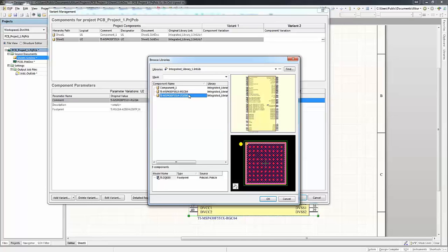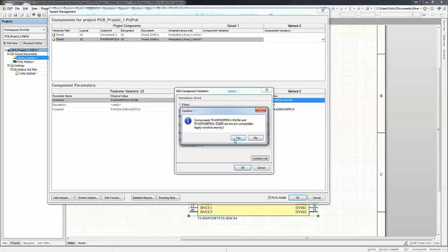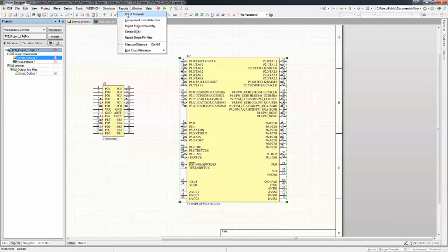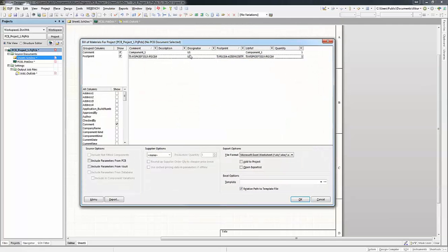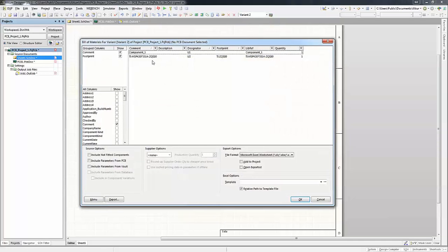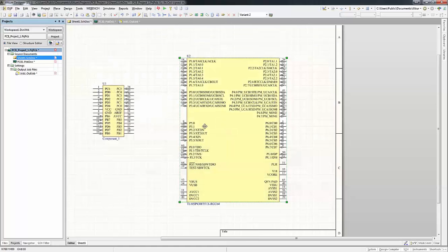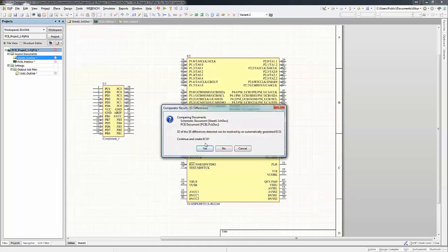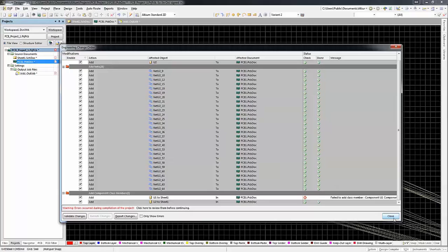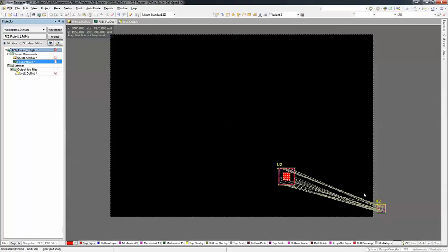what we call true variant management, because we can not only make a component fitted or non-fitted, but we can also choose an alternate part for that particular component, so that we bring in a different footprint if need be, right? A different footprint that maybe has a larger step body, but not necessarily a different pad, so that the pad matching would still match, right? So once you do the variant, it would also carry forward to the bill of materials as well, so that you get a proper procurement list for your list of components, right? Based on the variants of the board that you have.